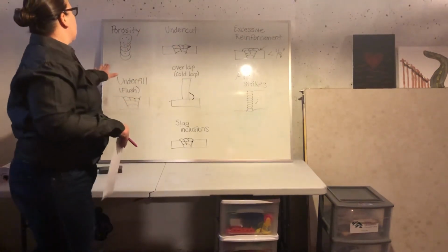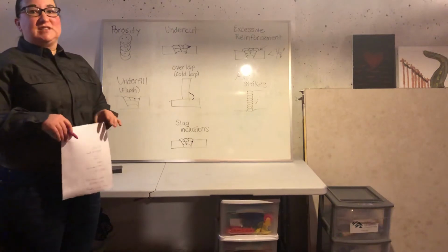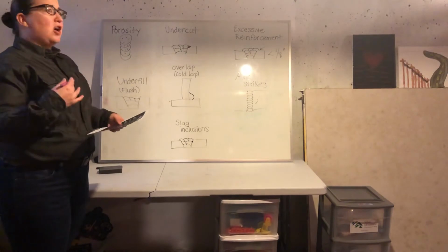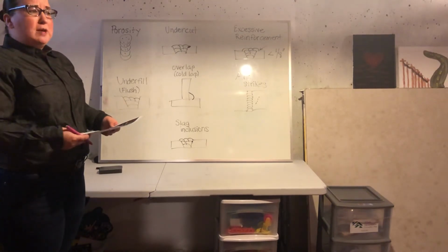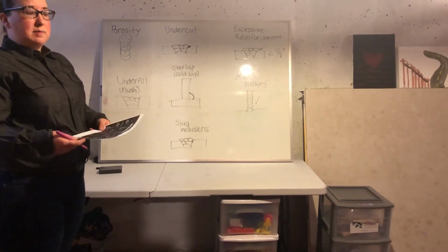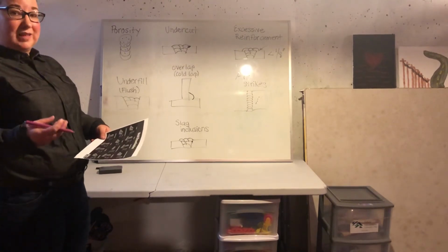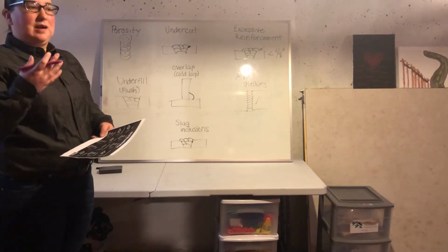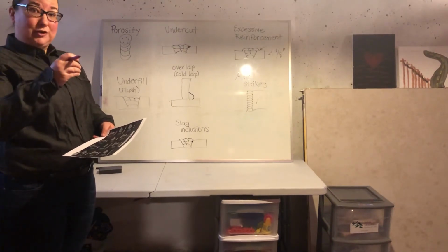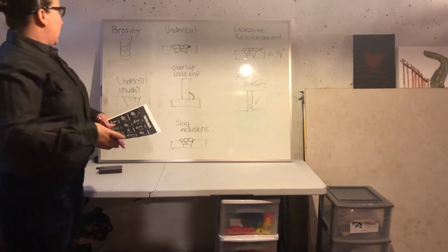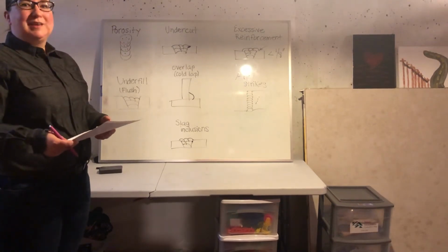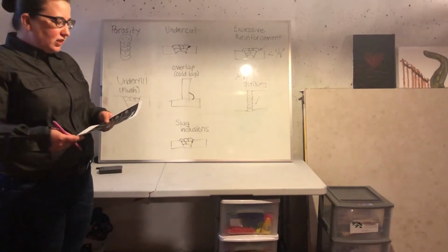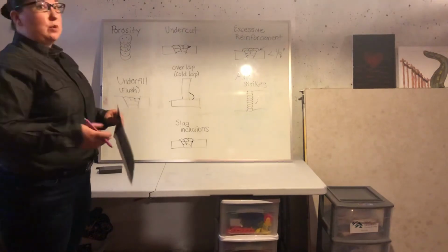So we'll start out here on porosity. I like to call this the Swiss cheese looking weld. Porosity can be caused by a few different things. Primarily in stick welding, it can mean a lack of flux on our electrode, whether it's chipped off or you're reusing an electrode and that bare end isn't covered any longer. We can end up getting some of that porosity because we're getting contaminants from the outside air pulled into our weld. Some other causes for that, we talked about that arc length.